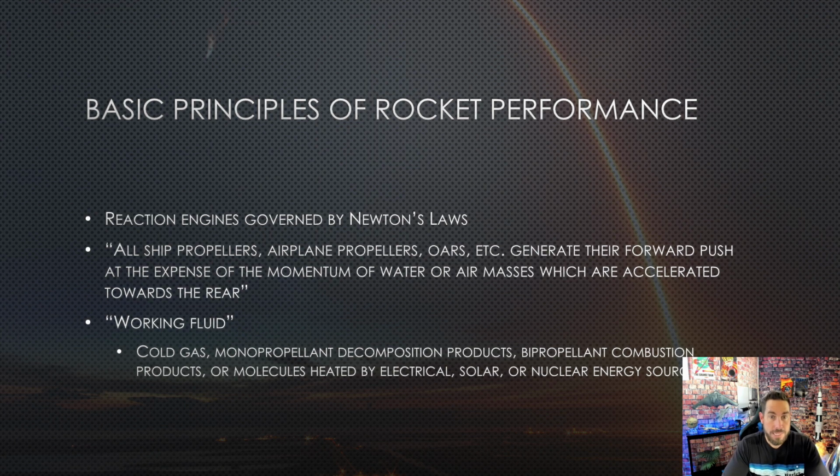All right, now a few basic principles of rocket performance and how all this starts coming together. Reaction engines or rocket engines are all governed by Newton's laws. One quote that goes along with it: all ship propellers, airplane propellers, oars, everything else, they generate their forward push at the expense of the momentum of water or air masses that are accelerated towards the rear. This uses the working fluid, and these working fluids can include cold gas, the decomposition products of monopropellants, the combustion products of bipropellants, or molecules that get heated by electrical, solar, or nuclear energy sources.